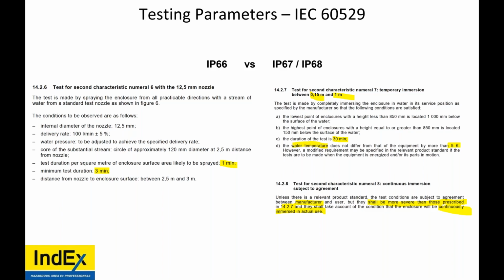Further than 10 meters, every 10 meters is an atmosphere. So it may say 2 ATM, 2 atmospheres, 20 meters, but it may also say IP ratings. Because like we said about IP ratings, IP68 does not mean you're rated for IP66. But if you're rated for IP68 and 2 atmospheres, hopefully you understand what I'm saying. Different testing techniques, requirements, require completely different testing.